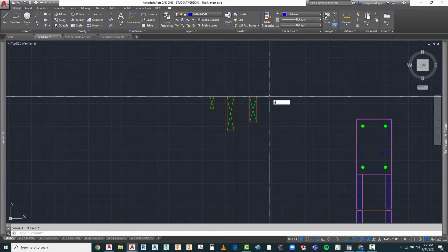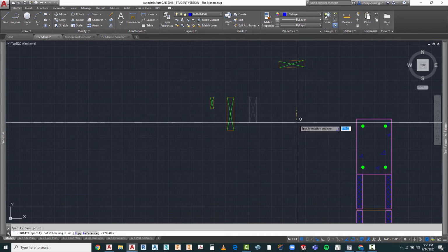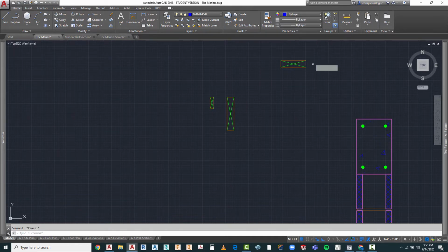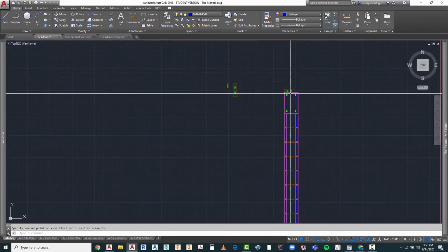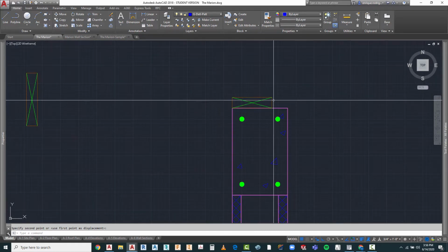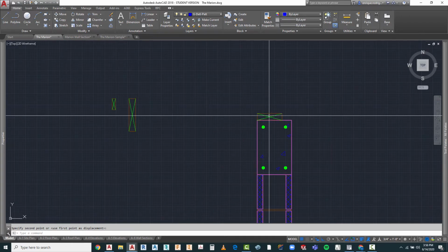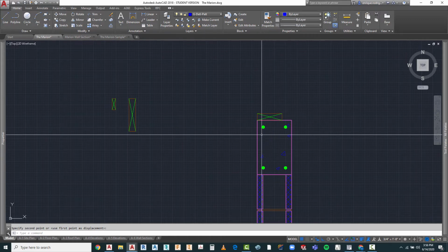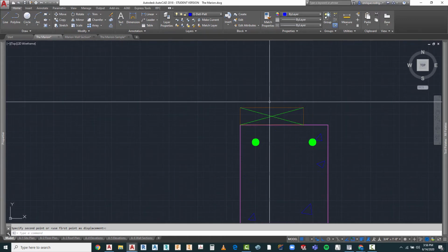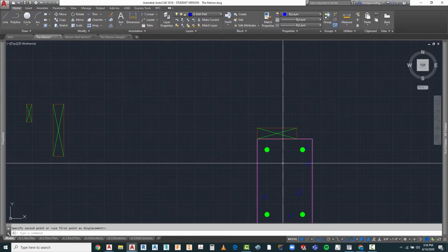So this represents my top plate. I'm going to rotate it, put my ortho on, and locate it right from this point, right in there. Now this top plate goes all the way around. Because we're in South Florida, and almost any location, this needs to be anchored solidly into this concrete tie beam that we have going around. So we place it in there and anchor it with what we call J-bolts down to the concrete. Now these J-bolts are located in certain intervals.